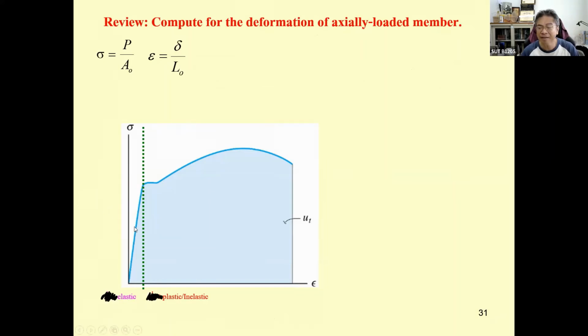Most of the time, elastic region going to be very small. In the elastic region, there is two important points: the yielding and the proportion. You got to be beware from the problem statement which one going to be, but usually they are equal.